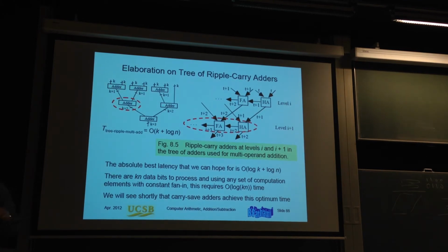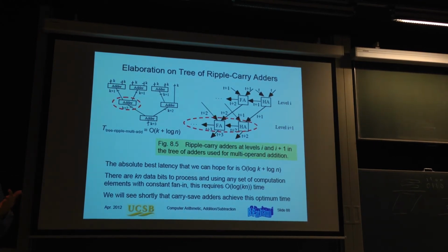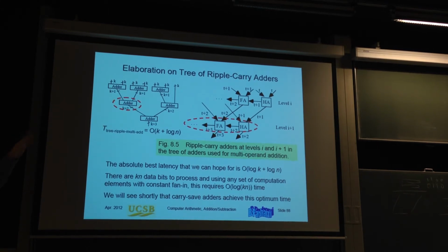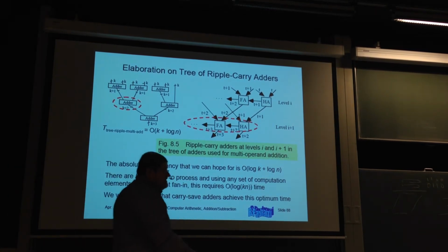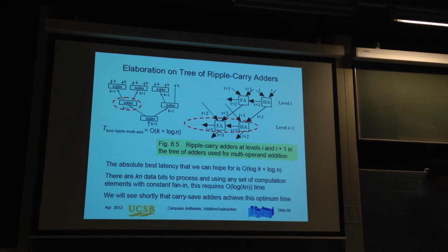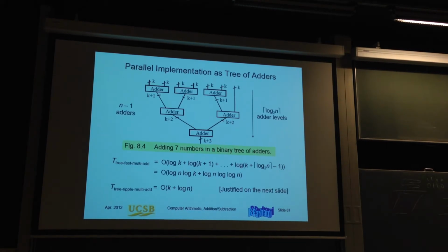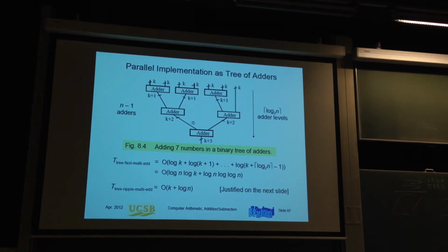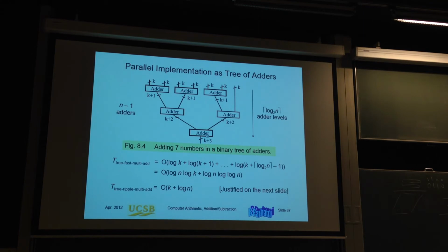From the point of view of the hardware effort, I won a lot. Because now I just have a sea of full adders, which are connected in this way, they have carries in, and also there are things which are transferred between the levels. There is a propagation, there is an activity in the system, which is now going like a wave. Then things are propagating in this direction at the same time. And this wave will complete things faster.